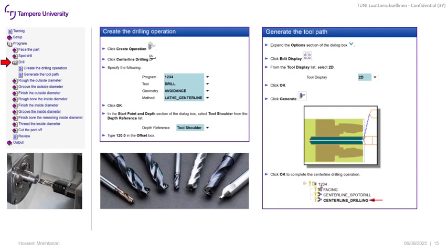using. It might be possible that sometimes we need to use another drill first to make the hole a little bit bigger. So for example, we can go from a spot drill to a drill of 10 millimeters in diameter, and then move to 20 if the material is hard or our tool is weak or if we don't have any lubricant or something like that. If not, in this case, we can go straight to the 20 millimeter.